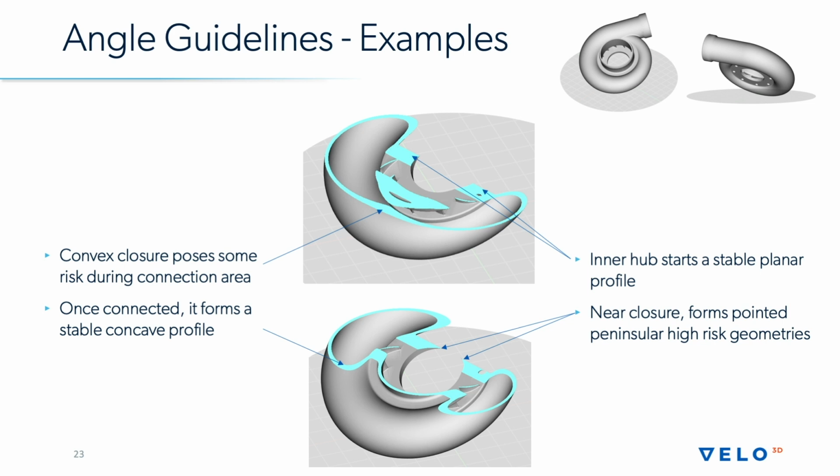So eventually, even with the closed loop control that we have to help mitigate some of these variabilities, you're still going to run into some issues with geometry. With extreme geometries like this, you're going to have too much energy put in. It's going to lose stability. And so the net here is that you have to add some supports to this type of geometry.